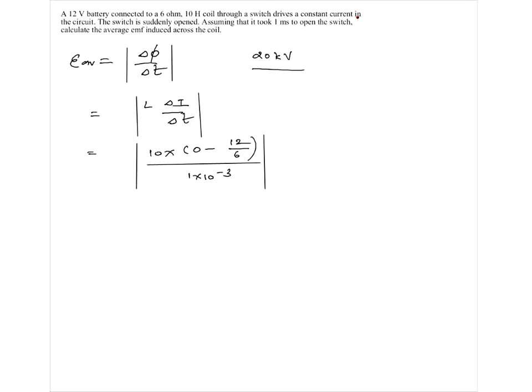For example, when you switch on geyser, watch carefully. You may see some light coming from inside the switch. That's sparking taking place. You may think that mechanically you have disconnected, but air is still there, and that air can conduct some current.